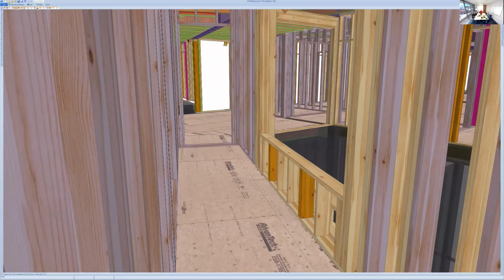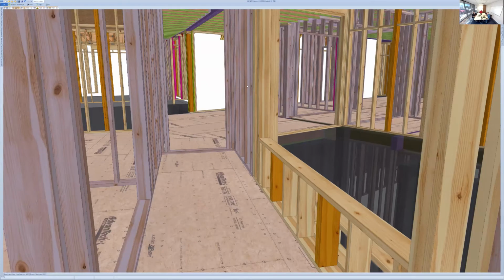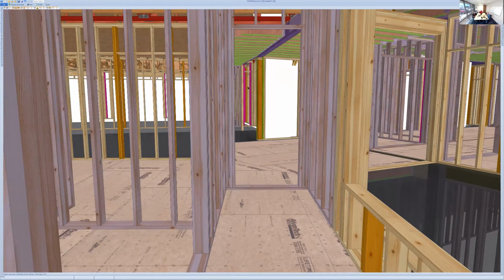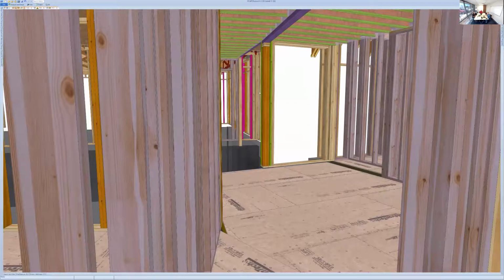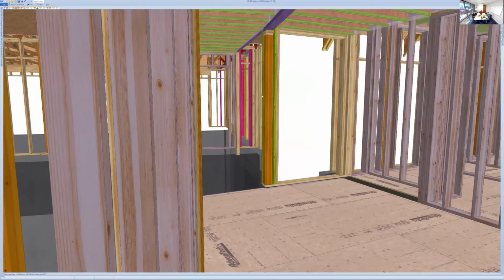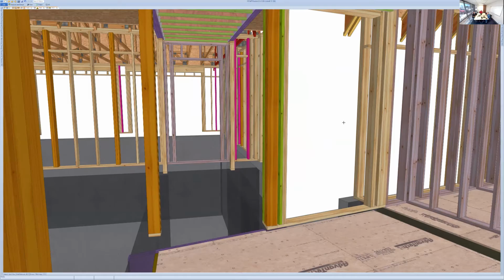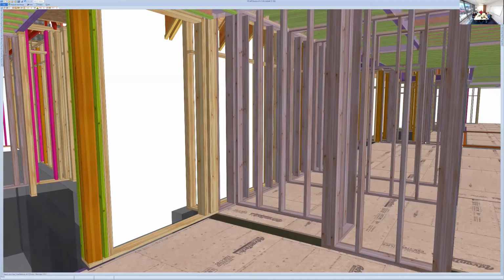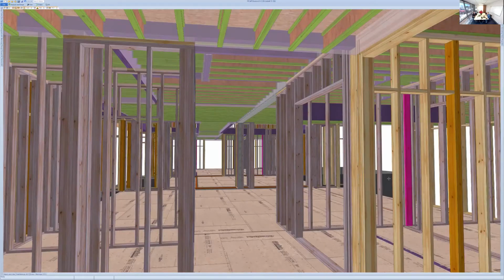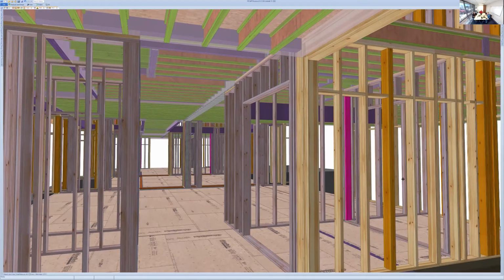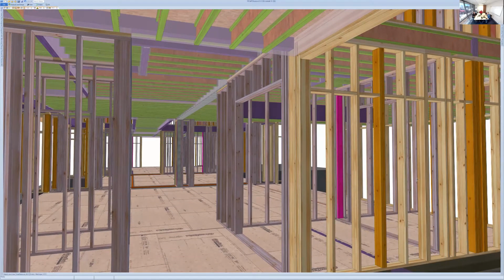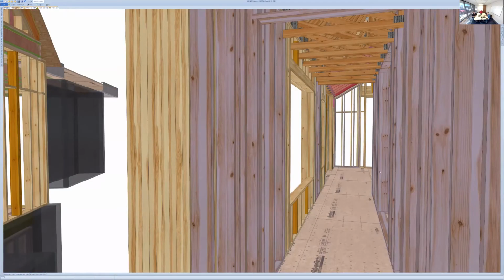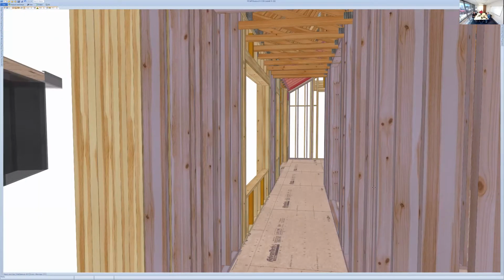So once we create this model, we superimpose the loads that the engineer of record will give us so that we can structurally design and engineer the floor trusses, roof trusses, and wall panels, and make sure that we're taking care of vertical load distribution, and the structural integrity of this building will be perfect, hopefully, by the time we get done with it.